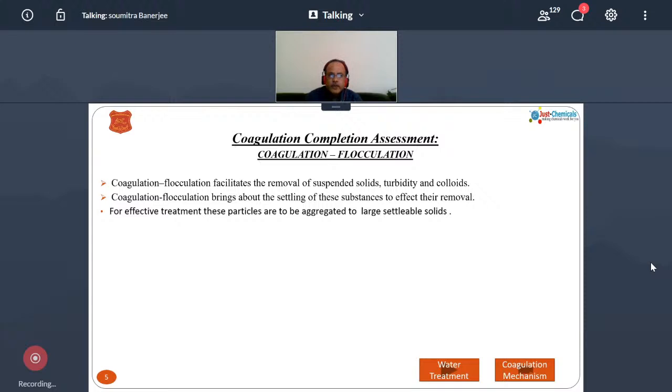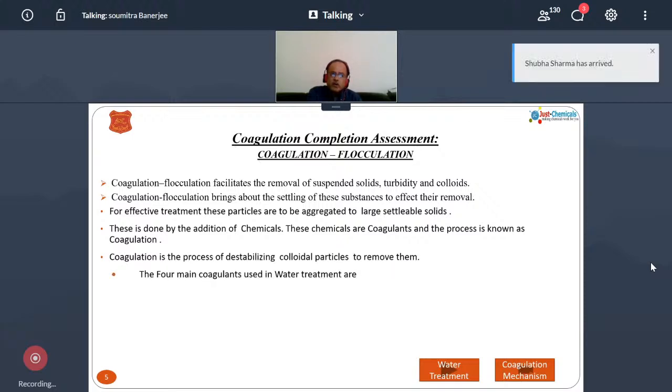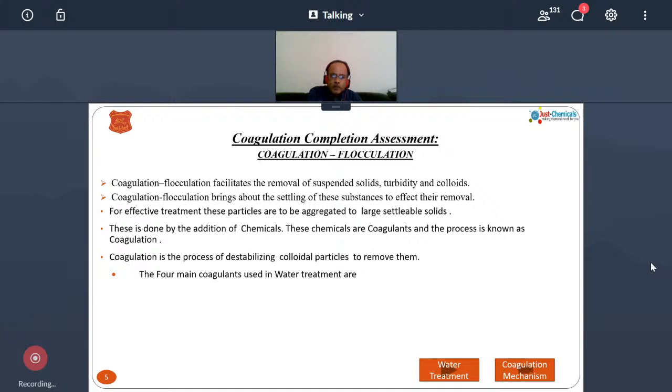In India, mostly it is the opposite: we add coagulants and flocculants to settle down the suspended particulate matter, but we seldom add any air because we have less oil and grease. Wherever there is high oil and grease, we have to add air so that the air makes the sludge come up and we can skim it.